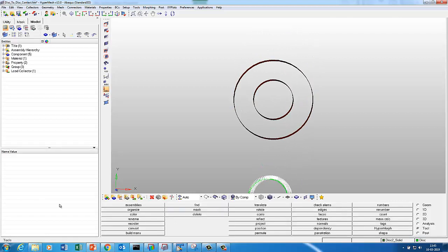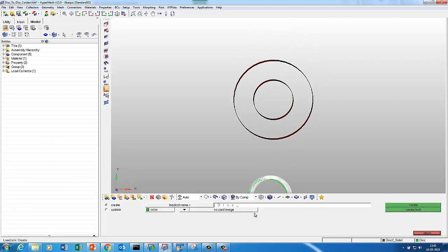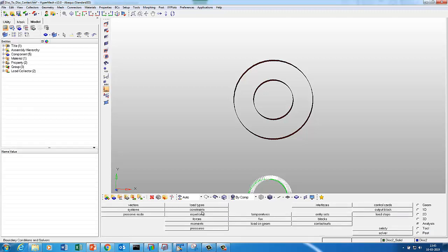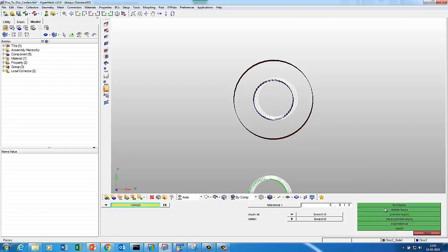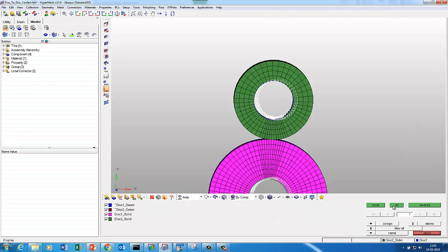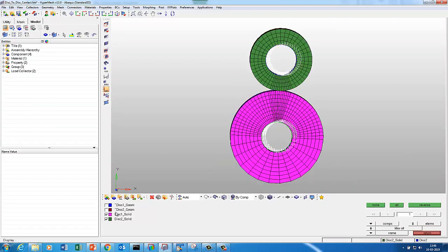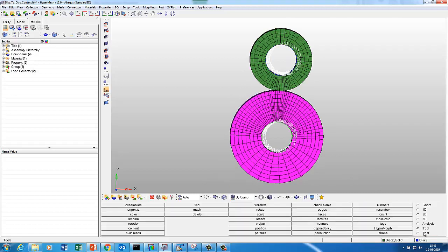Now I'll do this 2 boundary condition, I select some color, and I say analysis constraint, and I'm going to put this by 0.1 down. So along Y 0.1 down, others are constrained. Create, we are done with that. Now tool, faces, delete. Now we have everything. We have created the 2 components, we also defined the contact, friction, and the boundary condition.